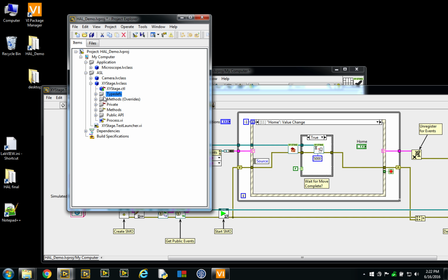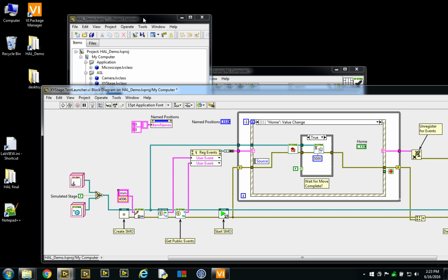In the degenerate sense, when there's no actual motion, if we assume that the motion is completed, we can just read the target position and substitute it for the real position, and that gives us a very quick way to assess if our logic for a positioner would work. For example, move absolute position would set those target coordinates, and then when we say read position, we would read the target. Therefore, we've already arrived at our destination. So this is a trick for simulating real world objects that I use very often.